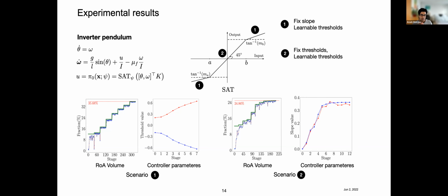When it reaches the stage where we know that the Lyapunov function cannot be improved any further, then there is one step of policy improvement. This policy improvement leads to an enlargement of the region of attraction. As you see, the region of attraction increases over the iterations of this algorithm until it reaches a point where it cannot increase any further, or we hit some physical limitations.